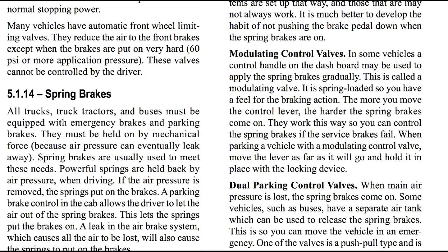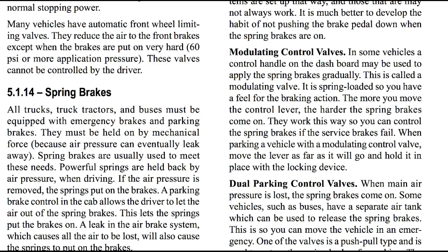Modulating control valves. In some vehicles, a control handle on the dashboard may be used to apply the spring brakes gradually. This is called a modulating valve. It is spring-loaded, so you have to feel for the braking action. The more you move the control lever, the harder the spring brakes will come on. They work this way so you can control the spring brakes if the service brakes fail.